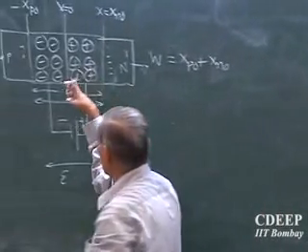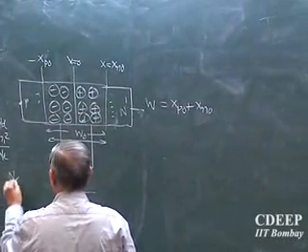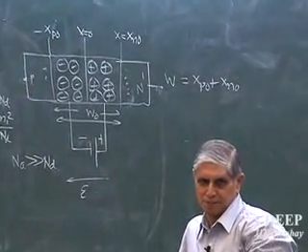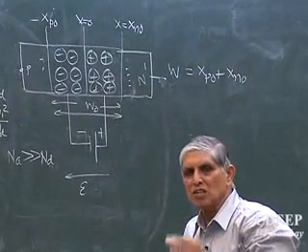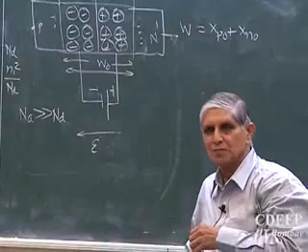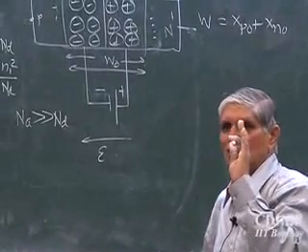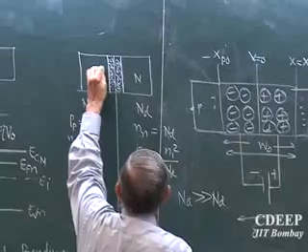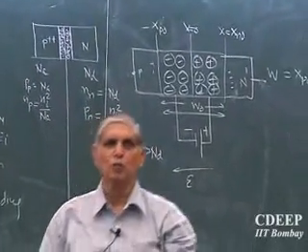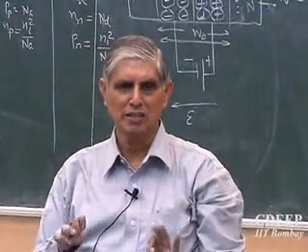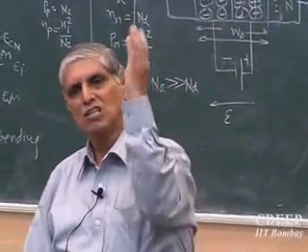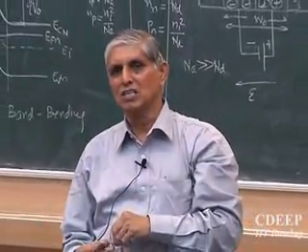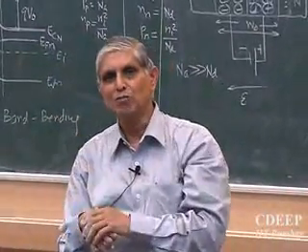Before we go ahead, let's say NA is much larger than ND. What does that mean? For the same cross-sectional area, think of what I said. If NA is much larger, which junction am I talking about now? Let us say a P++ N junction I am making: heavily doped P compared to lightly doped N, and I join them. The cross-sectional area is the same for both sides. So for the same amount of charge to balance, what should I get?